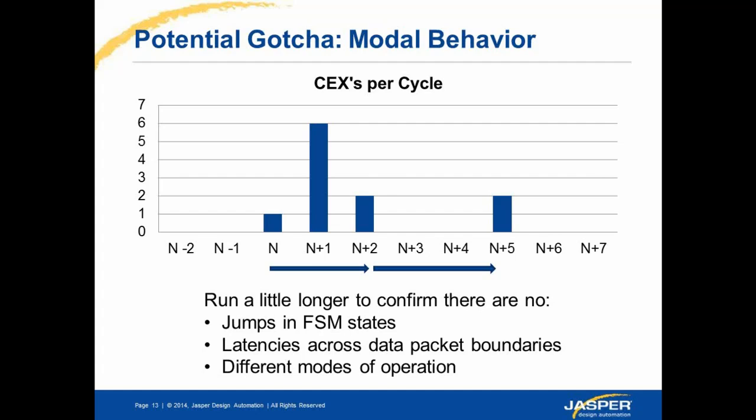So it will come back to you with a number, let's say 30 or 35, and say, okay, there is a cover point in your RTL which is being hit at a depth of 35, and let's say you've just run it till 20 or 24. So it says, okay, we've found a couple of cover points which are being hit at, let's say, 28 or 32, and you've just run it till 24.